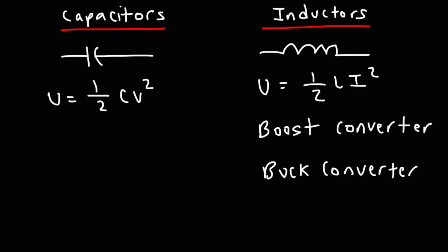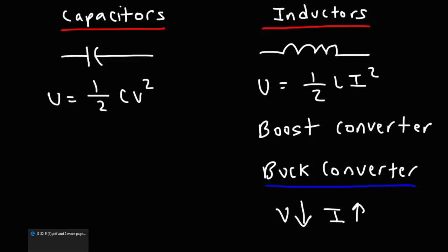We're losing energy. But when you use a buck converter to reduce the voltage, it's more efficient because as you reduce the voltage, the current goes up. So that's one advantage of the buck converter circuit over the potentiometer voltage divider network. With the boost converter, you can increase the voltage of a DC power source greatly. You can turn a 9-volt battery into a 100-volt power source.